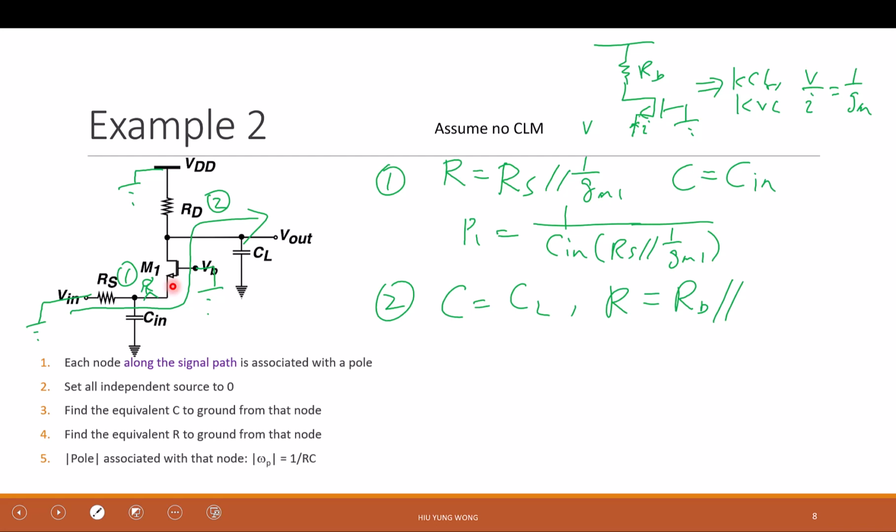We use this voltage controlled current source in the small signal model, solve a difficult KCL, KVL, and found that indeed looking into the source is different from looking into the drain, although from a DC perspective they should be symmetric, because we are in the saturation regime.